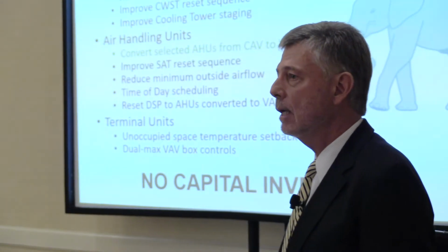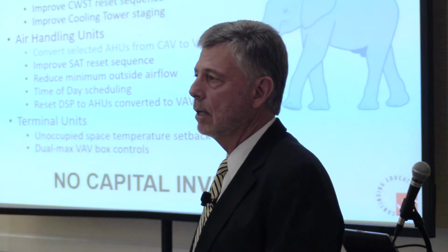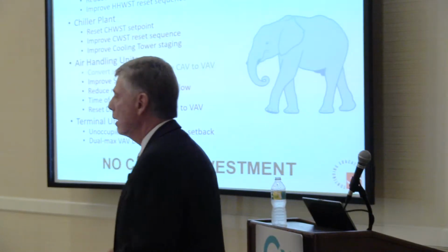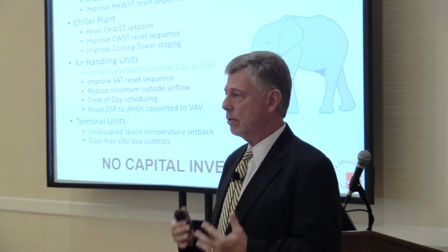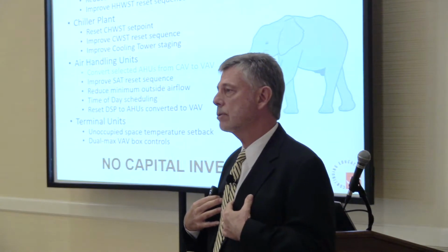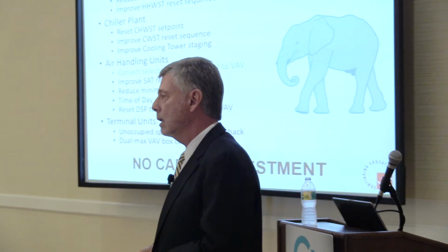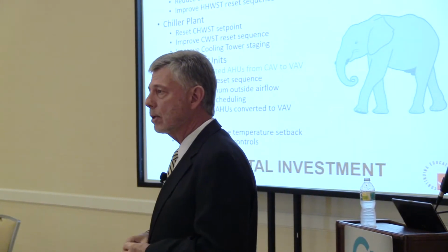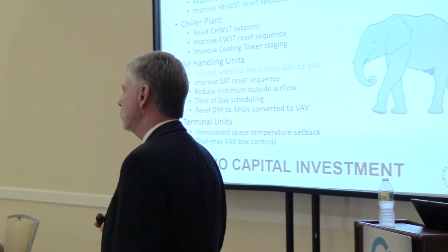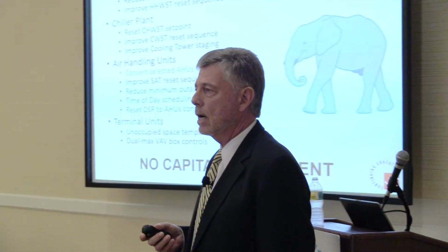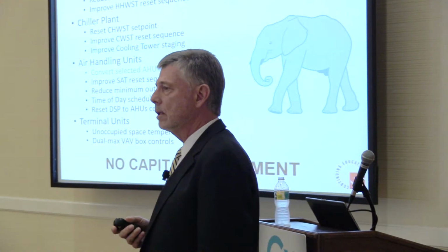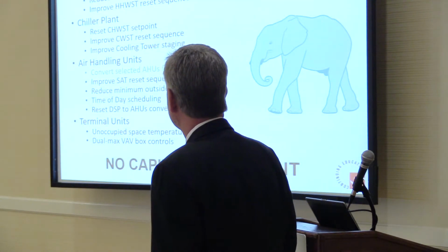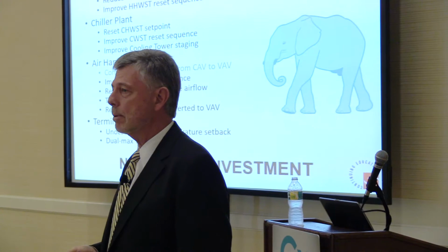So that is a very key thing in making this endeavor pay back and have a return on investment that the C-suites will accept. Because really the only fees involved are the fee for us to push this process, to work with controls contractors to provide the new programming per our direction, and some test and balance work. There is a little bit of mechanical modification that is sometimes required. We're not sure that it will be required all the time, but it is not an expensive endeavor. But it has to do again with that pressure relationship back in the return side of the air handlers. So no capital improvement, no capital investment.